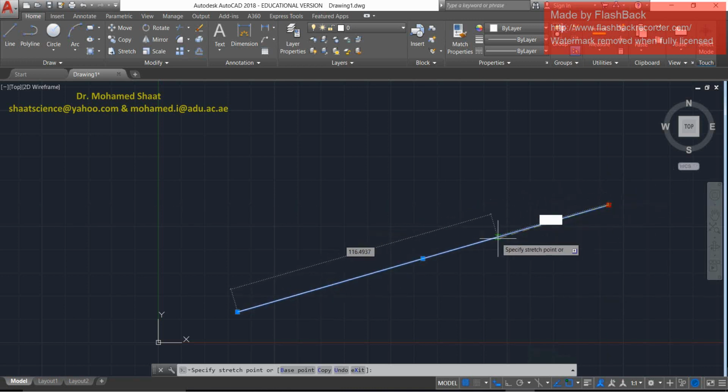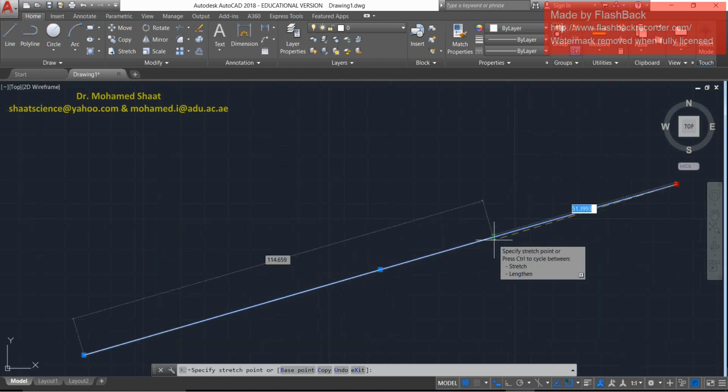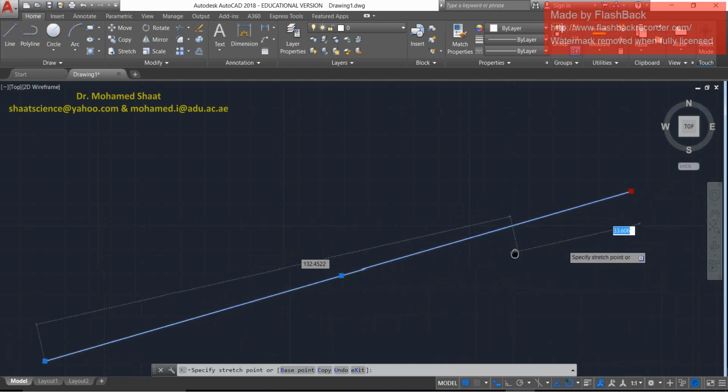But you have to make sure that the snapping is already shown. The O-snap should be shown like here. As you can see, there are 2 small green triangles touching each other at the vertex. This is known as the nearest snapping. Nearest means that you're going to move this point by sticking to the line, or you can extend it further.